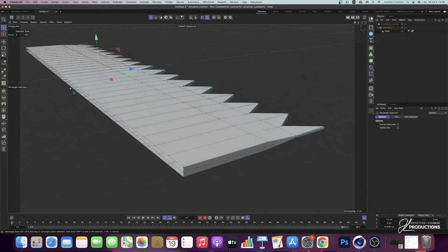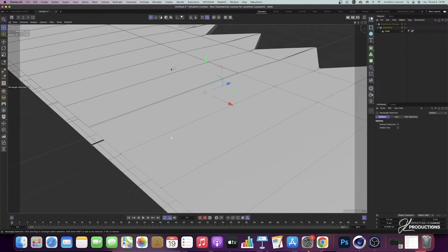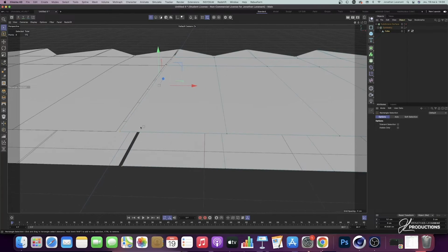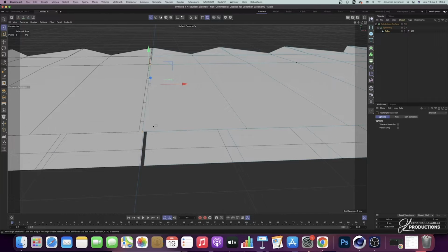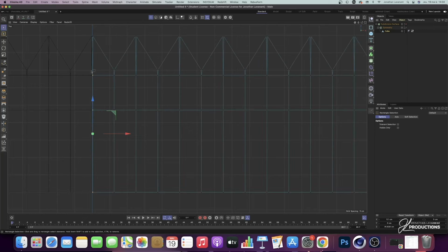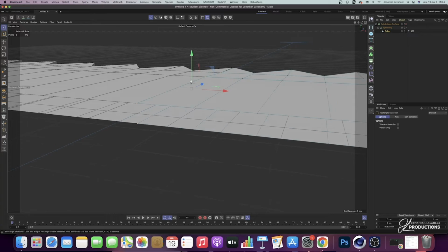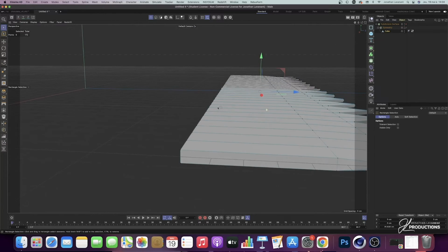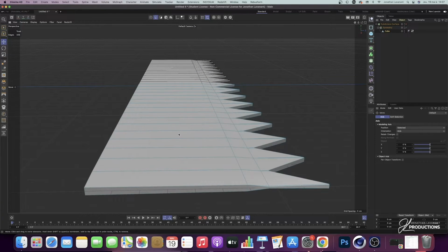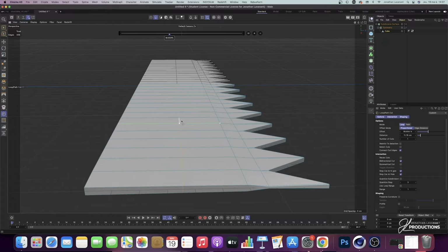So, if we go back to 3D view and look here at the level of symmetry, we can see that we have a small error because in fact, the points are not perfectly in the center of the scene. So there, what you have to do is go back to top view. Select all the points that are here and at the level this time of the displacement in X. So not the scale. They must also be reset to be able to put the points back perfectly in the center. So there, when we did that, we can see that the symmetry works perfectly well.